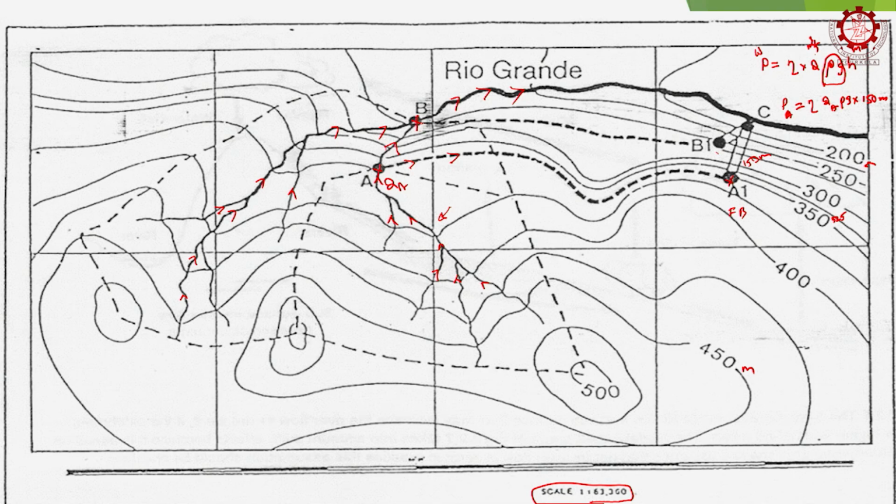He suggests we tap water at B, take water along this canal to B1, which is at 275 contour height, and then locate the power plant at the same place C at 200. But now, our power plant has a head of 75 meters only, but Q at B will be larger than Q at A. So, there are two options now.